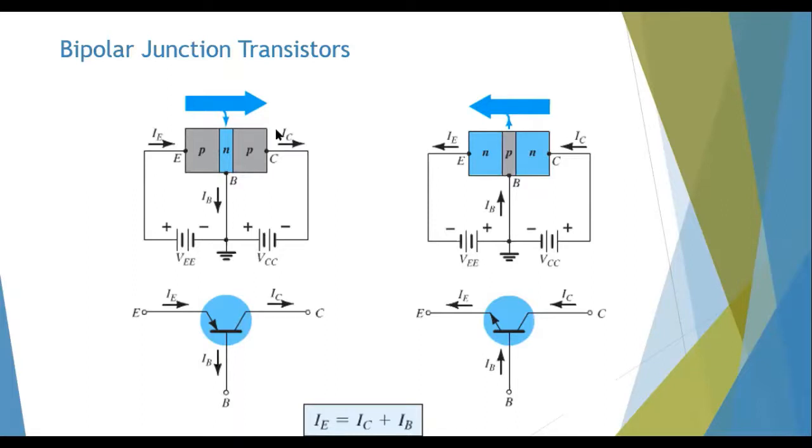We very well know that the direction shown for conventional current is a flow of positive charge. By convention, before electrons were discovered, people were thinking that actually current is a flow of positive charge. So since what is flowing in a PNP transistor is actually positive charge, because the emitter is a P region, this is why the arrow is shown along the direction itself. So the emitter is sending positive charge away from it, so the arrow is away from it. You see? So let me just repeat that, very important.